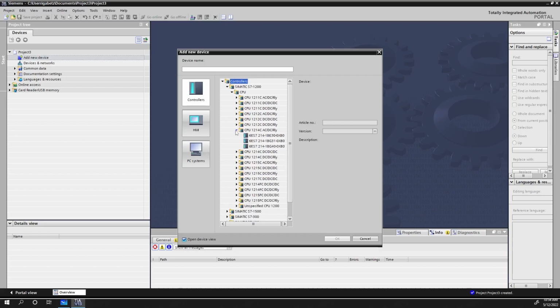Now, some of you may be asking yourself, what does the AC-DC relay mean? Well, AC is the power input onto the PLC. If I didn't talk about this in the last video, we take 120 volts AC as an input for these PLCs. DC is the input section, so what type of input signals it is expecting from push buttons and things like that. So that is 24 volts DC. And then the relay is the output. So that is all those outputs. I did mention how we could put 24 volts or 120 volts of AC into those. We will be using 24 volts this semester.